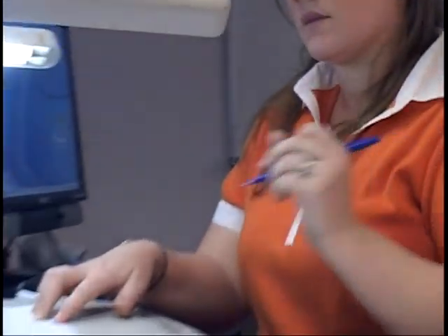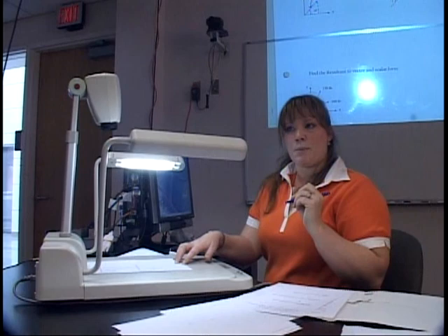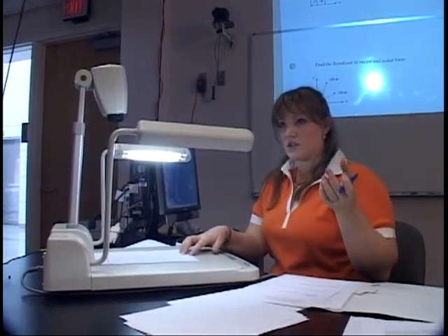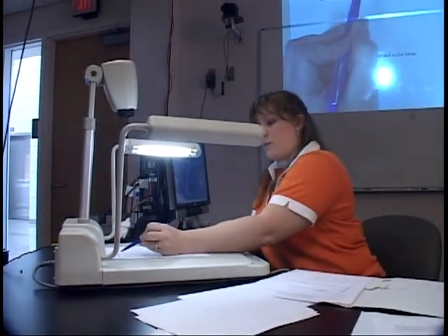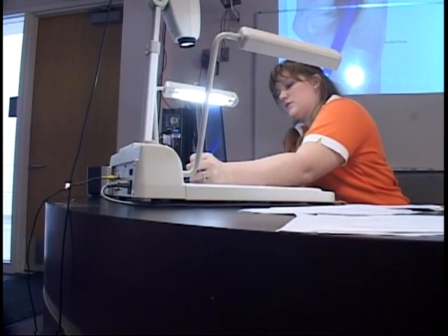So what you want to do whenever you get these situations is think about this as a triangle. And on that triangle, the 50 kip force is going to be the hypotenuse. If you want to think of it like a length, the length of the hypotenuse is 50 kips, that's fine. What we're looking for, because we want the components, is the x and y.